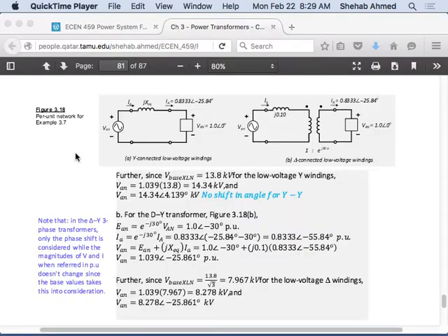That's the only trick in this one, really. Then after you calculate the phase voltage, you just multiply by the base and you get the actual value. And of course, the angle does not change. The base quantities do not have angles; they're only magnitudes.